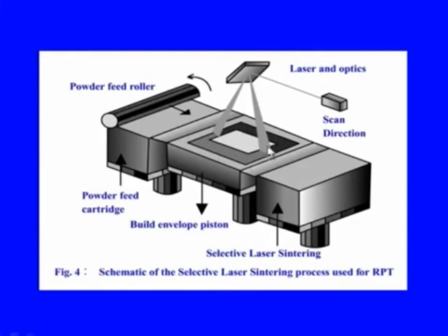Say for example, here it is shown the rectangular area. So, the laser can be made to be incident on this area of interest as per the program. Now, the area on which the laser is falling will get heated up, melted, and the powder particles will get fused like this. That means, it will form a layer by themselves.